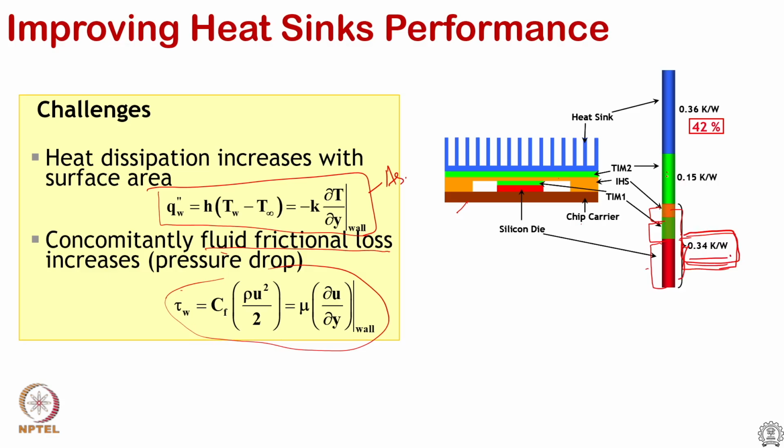On the other hand, one has access to this thermal interface material and also access to the heat sink solution. So, the heat sink solution in this case contributes to 42% of the total thermal resistance. This is Tj and this is your T ambient, and so this is your T case. So, you have a thermal resistance of T case, junction and ambient.